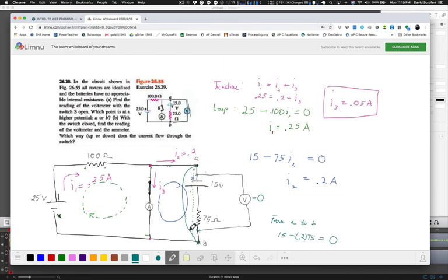This in and of itself is a path. So if there's no resistance between this point and this point along this path, then the voltage drop along from here to here has to be 0. And since this whole path is parallel with that whole path, it must have the same voltage difference across it, and that in fact is 0. So yeah, it's consistent. That's the point I want to make here.